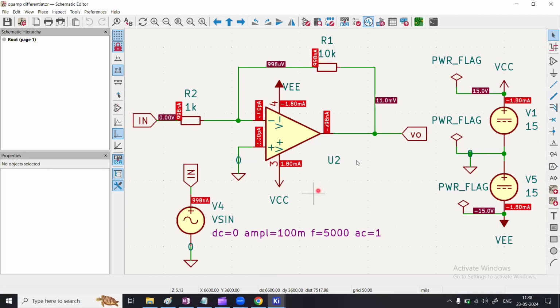Before that, you also see that all these currents and voltages, voltages in brown and currents in red, have been annotated back on the schematic. That's done when you finish the operating point analysis. Whenever you do the analysis, you will have all this wealth of information. Now we can read and understand more and more from this schematic. So in a moment we'll do that.